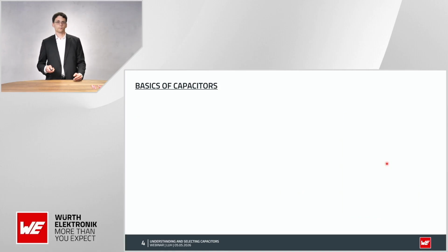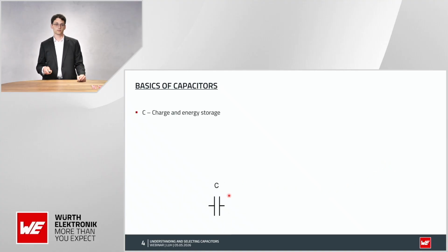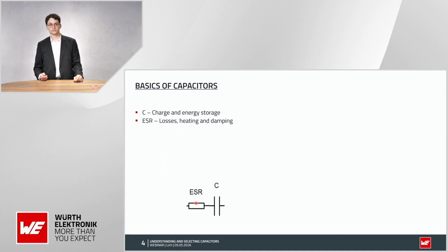But a capacitor is not only a capacitor. We have the capacitance, which gives us the benefit. It can be charged and it can also be used as energy storage. But we also have, for sure, some losses, which are described with the ESR. The ESR is mainly the reason why we have some heating inside of the capacitor, and this can also limit the lifetime.